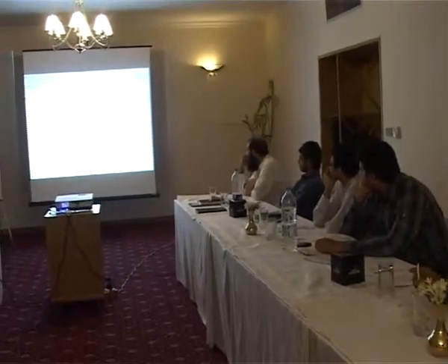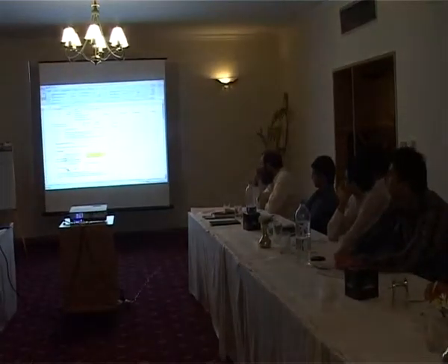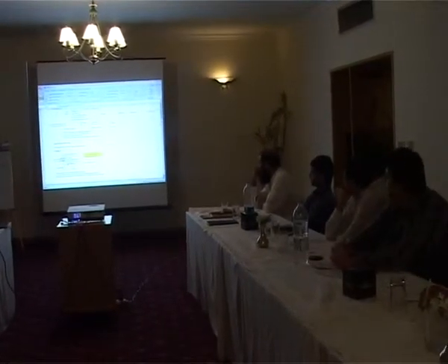This here gives 180 centigrade, you see up here the calculation. This here is absolute zero and the 180. Then we have 25,400 cubic meters per hour that's going to pass through this chimney. That gives 7 cubic meters per second of flue gas at 880 centigrade, and with 18 meters per second of velocity,